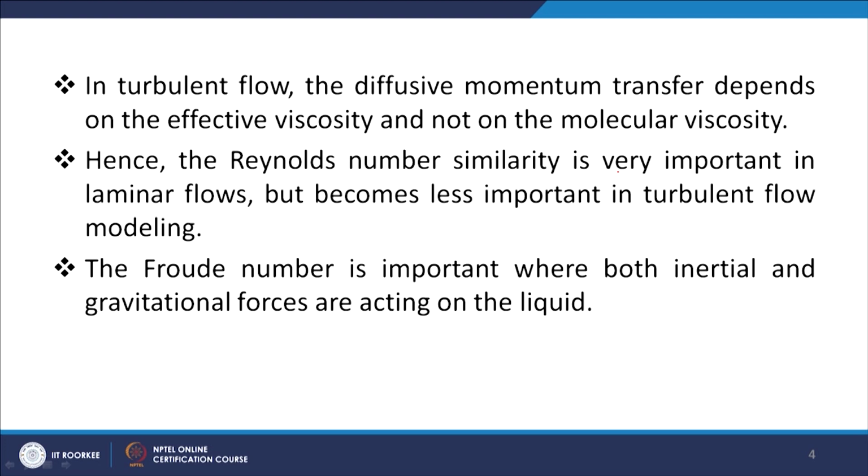So, in the turbulent flow the diffusive momentum transfer depends upon the effective viscosity and not on the molecular viscosity. When we talk about the effective viscosity, it will be nothing but the summation of the molecular viscosity and the turbulent viscosity. So, the diffusive momentum transfer which will be calculated is based on both these factors, the molecular viscosity as well as the turbulent viscosity.